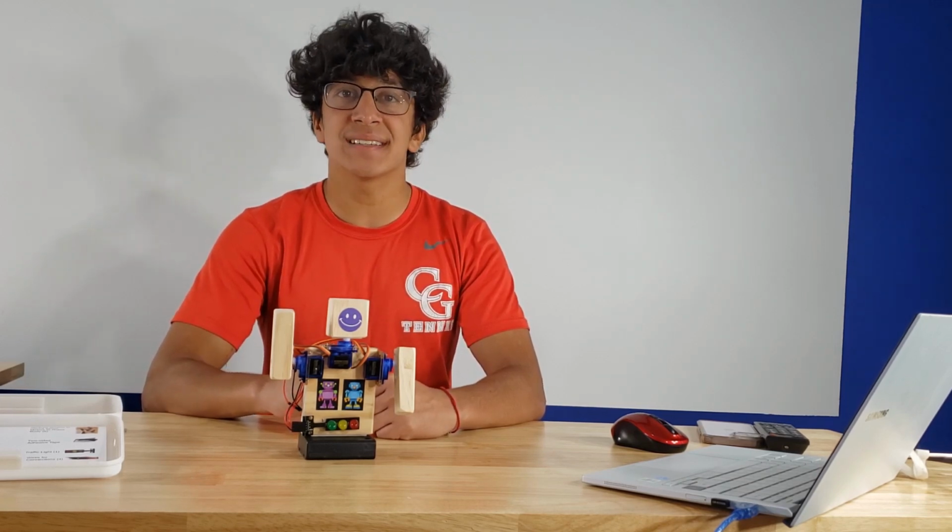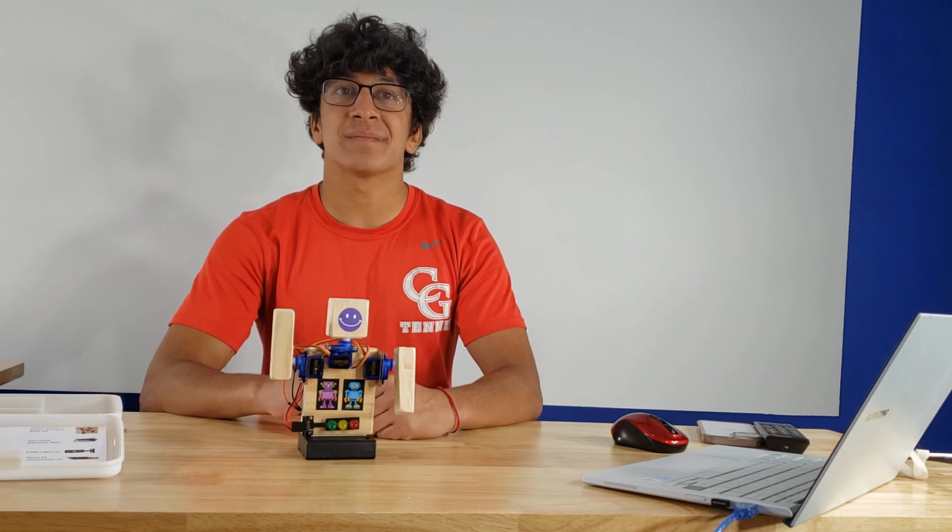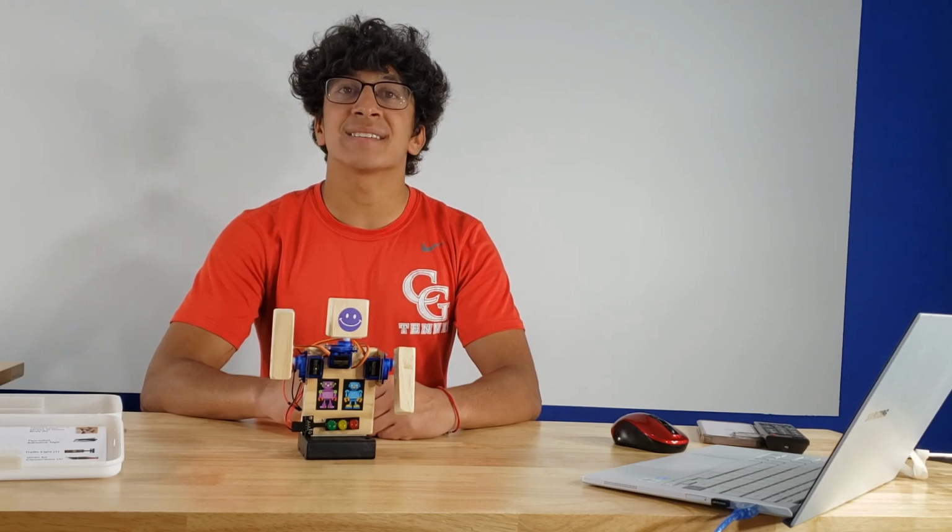That's all. Easy, right? To summarize, the code starts with declaring the variables and naming the motors. The code inside the void setup section first tells the program which pin on the microcontroller unit the motors are connected to, and sets the initial motor positions. It also states that pin numbers 5, 6, and 7 are to be used as output pins. The code inside the void loop creates the movement of the left arm, the right arm, and the head based on the specific color of the LED that is on.